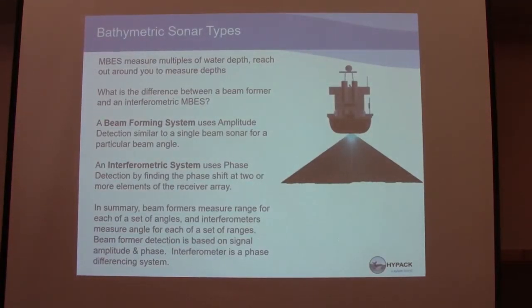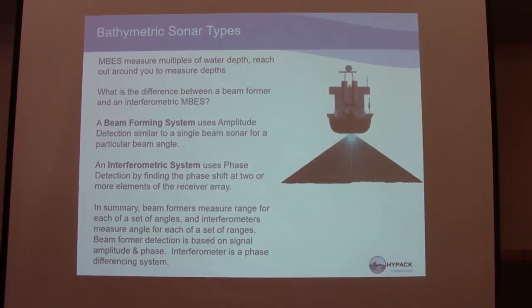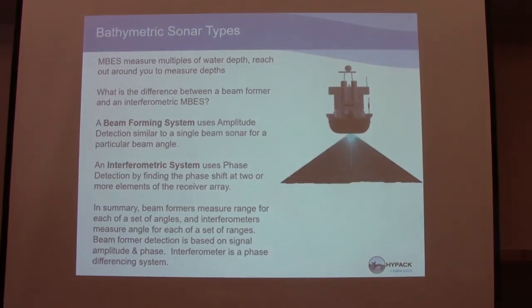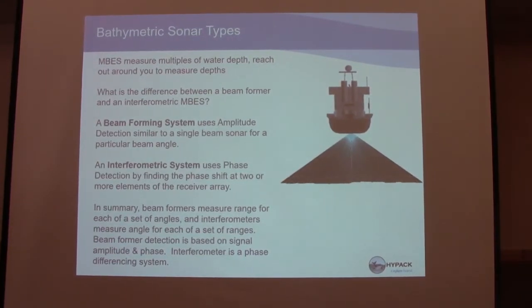These are the different types of multi-beam sonars that are out there. They're beam forming or interferometric. The beam forming uses the amplitude and the interferometric uses phase detection. The only thing I can say about that is that interferometric systems are relatively new to hydrographic, to our world. From what I understand, side scan manufacturers have gotten into bathymetry with interferometric technology. They've turned a side scan into a multi-beam.